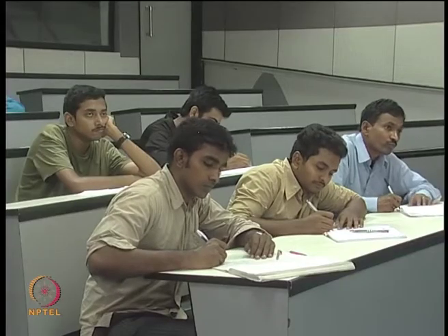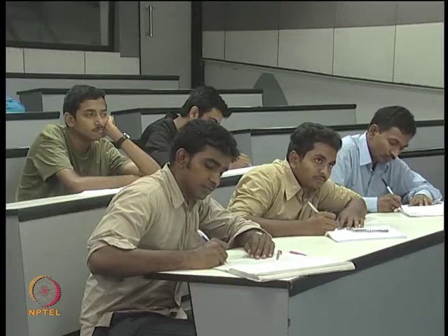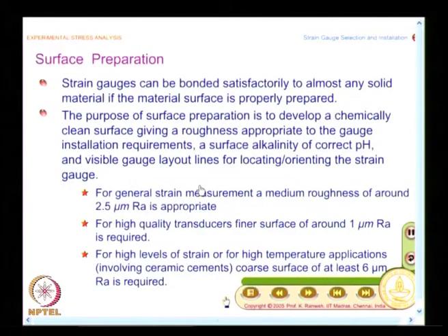If you have a misalignment, you will measure only strain along that direction, it cannot be interpreted to your direction, then you have to do a strain transformation law. For strain transformation law, you need to have pasted a strain rosette at the point of interest. So, strain gauge alignment is very crucial, it is not trivial. That is the reason why the strain gauge carrier comes with markings on it.